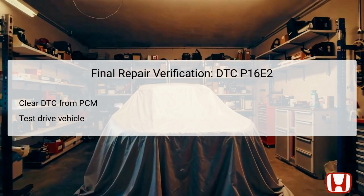After implementing the necessary repairs for DTC P16E2, it's essential to clear any stored DTCs from the PCM to ensure that the error is reset. Once cleared, conduct a test drive under regular operating conditions to verify that the communication errors have been resolved. Monitor vehicle performance and check for any warning lights reactivating. If the previously stored code does not return and the vehicle operates smoothly, it indicates successful repairs.